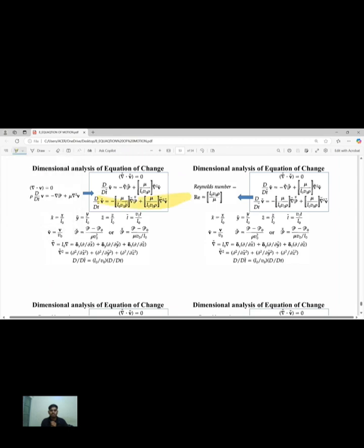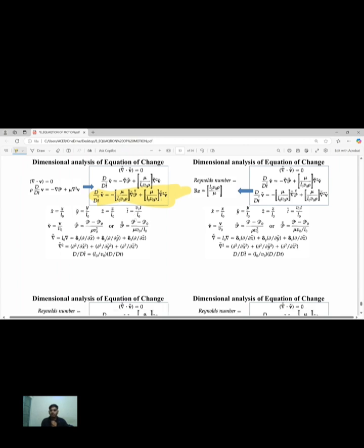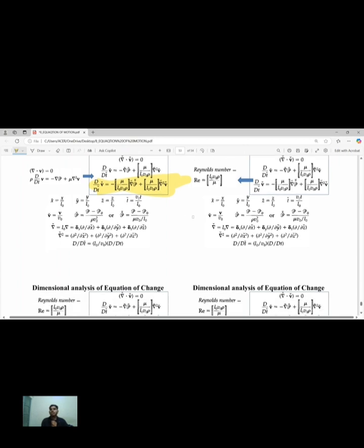So this equation we are getting, which is ∂/∂t̂ of v̂ is equal to minus μ upon L₀V₀ρ ∇̂p̂ plus μ upon L₀V₀ρ into ∇̂² v̂. So we have seen that in this case Reynolds number is equal to L₀V₀ρ by μ.